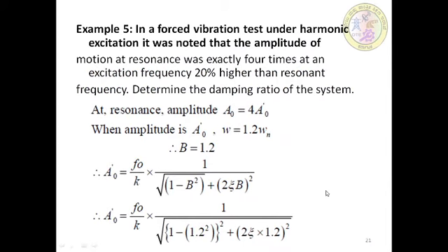Now the next example. In this problem it is said that in a forced vibration test under harmonic excitation, it was noted that the amplitude of motion at resonance was exactly 4 times the amplitude at an exciting frequency 20% higher than the resonant frequency.